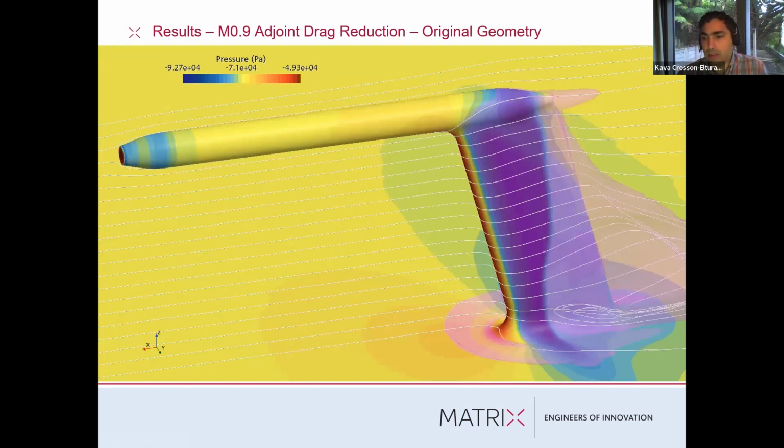Okay, so this is the initial starting geometry of the Pitot tube. You can see the flow field here. You can see that there's kind of an extensive wake with recirculation and a bow wake as well. You can see this horseshoe wake. And I'm going to cycle through and just go to the optimized geometry and keep an eye on that wake structure as I flip through.